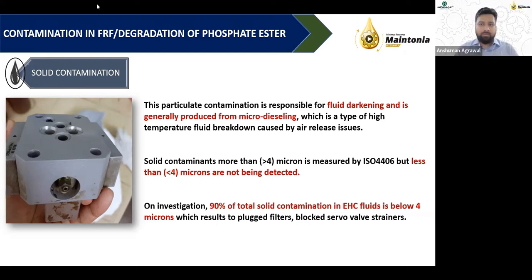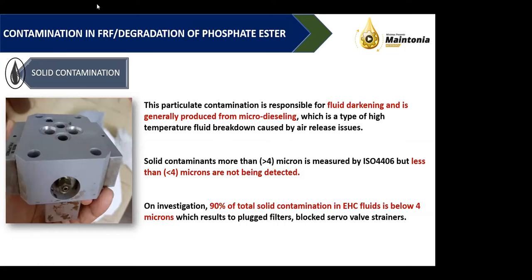Right, right. And is it also because these one-pass pencil filters inside these valves are of more than 50 micron, while we are assuming them to be of very fine nature, but because they are main line or full flow filters, they are not as fine as we are assuming? See, these filters are a very inferior component compared to the Moog valve, and no one would like to change the entire valve because of this small filter choking. So normally these are very coarse in nature.